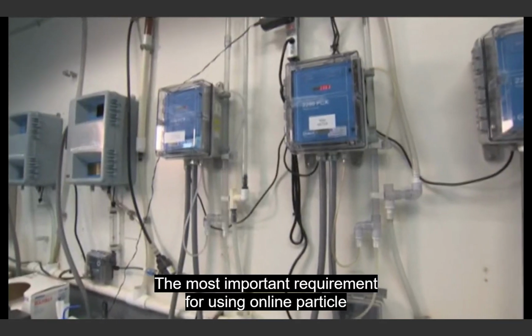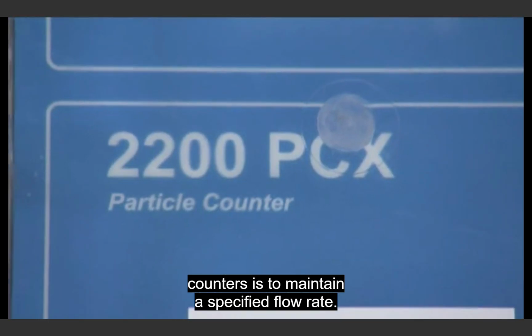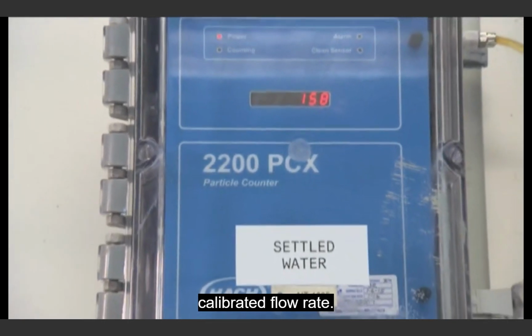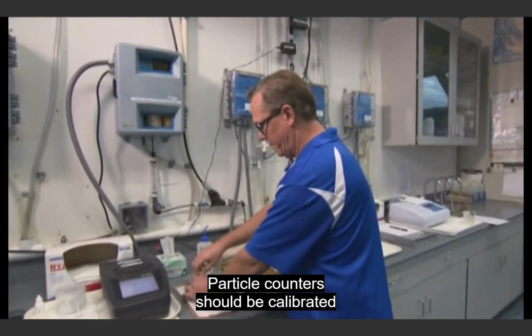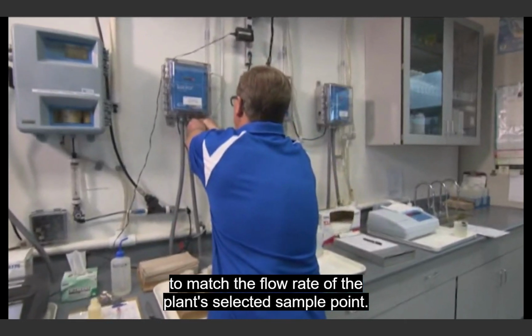The most important requirement for using online particle counters is to maintain a specified flow rate. The flow must be constant and at or near the sensor's calibrated flow rate. Manufacturers offer a wide range of flow rates. Particle counters should be calibrated to match the flow rate of the plant's selected sample point.